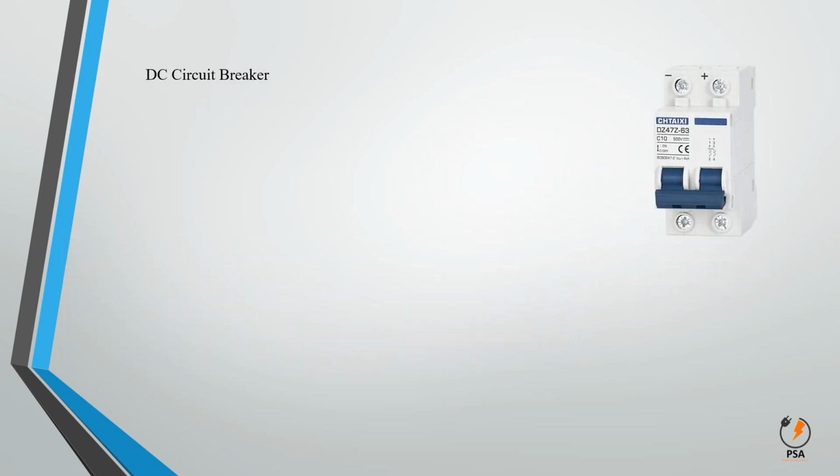DC circuit breaker. A DC circuit breaker protects electrical devices that are operated with DC current. It has additional measures to extinguish arcs. These technologies are relatively new to most homeowners, as most appliances in homes are AC powered. These circuit breakers use 24-volt DC to 48-volt DC. Although both AC and DC breakers look the same, they operate very differently internally. When an overload occurs, the internal contacts of AC and DC circuit breakers are separated to protect the circuit.